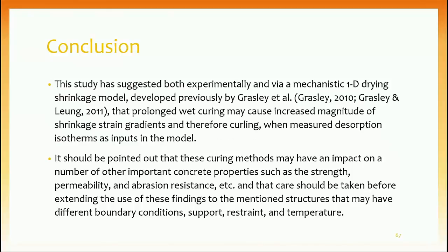So the study showed, both through the experiment and the mechanistic one-dimensional drying shrinkage model that was developed by Grasley's team, that prolonged wet curing can cause an increase in the magnitude of the shrinkage strain gradients and therefore curling. And all of this can be easily done by measuring the desorption isotherm as the input parameter in the model. But it should be pointed out that